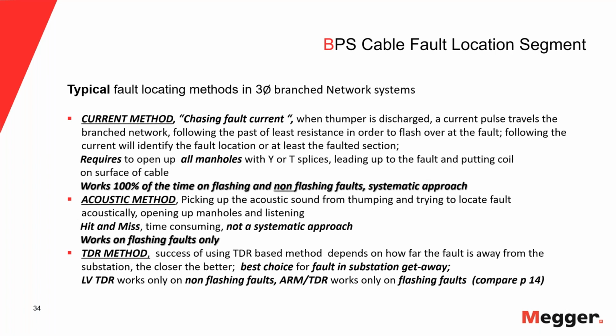So let's talk about that. And the good thing is it works for flashing faults or non-flashing faults. Even if I had a short circuit somewhere, when I put my thumper on, that current still goes through the cable. I still can pick that signal up, okay? Very, very important, because with the acoustic method, if I don't have a flashing fault, I hear nothing. So I can forget about it.